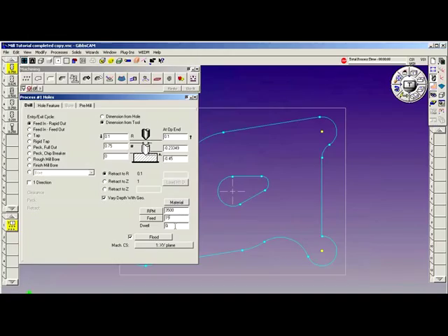If I introduce a dwell, 0.25, this will generate a G82 canned cycle. A G81 cycle is generated with the feed in, rapid out. A G82 is generated when you have a dwell. In this case, I'm going to dwell for a quarter second at the bottom of the drilled hole to make sure I get some good cleanup.